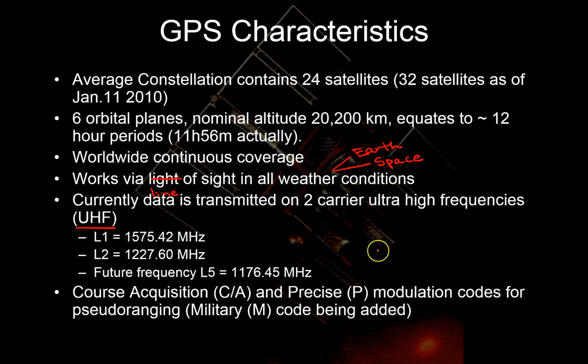So we have our carrier frequency. We can just think of that as a sinusoidal wave. Now there's 2 of these at different respective frequencies. Let's just say that this is the L1 frequency. And then what we say is modulated, or basically information is added to these carrier frequencies. So the carrier frequency itself is of no interest, at least in our discussion today. That's not exactly true.